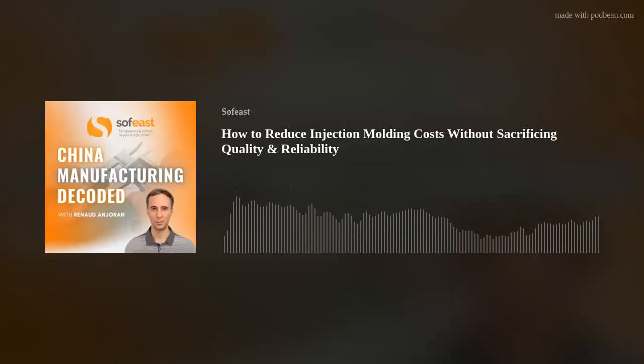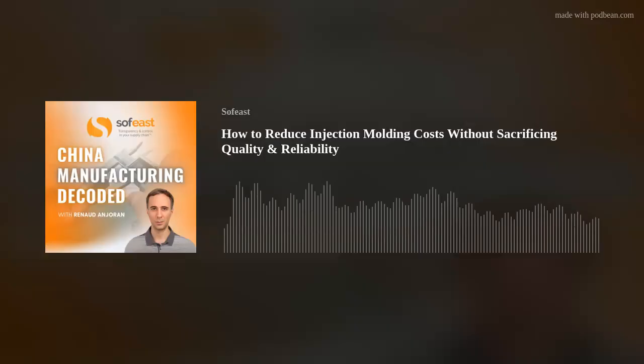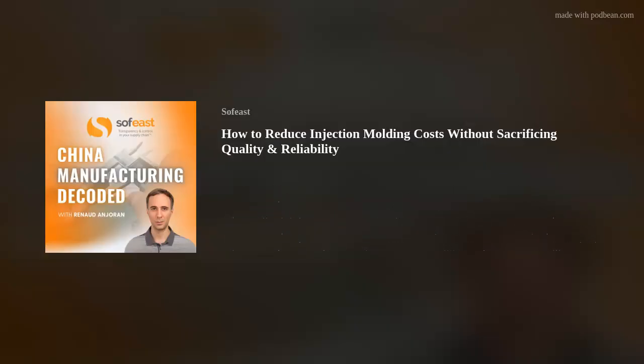So you've got one part that's working really good, you've got a couple of the smaller parts not working, so you've got an imbalance with respect to when you are actually molding. How do you overcome that? Well, you've got to mold more and throw stuff away. And so it really doesn't work. So sometimes you do need to invest in single tools for single components, or similar size if you're doing a family mold, in order to make it more cost effective.